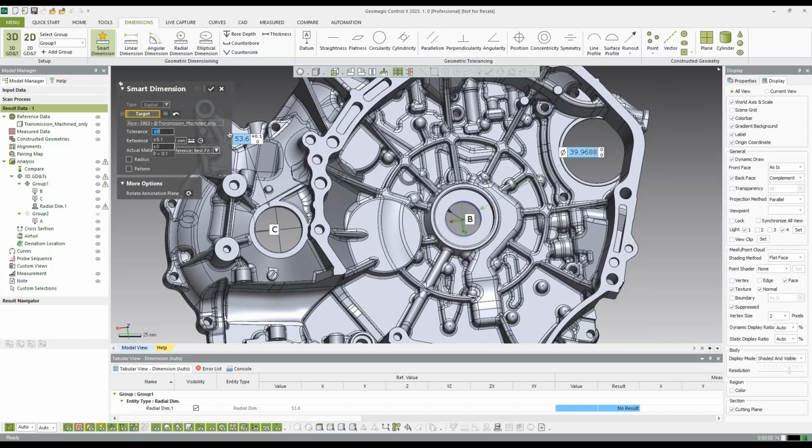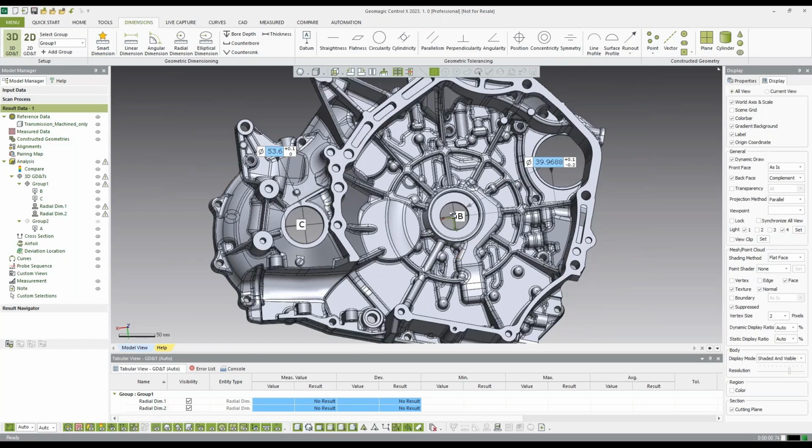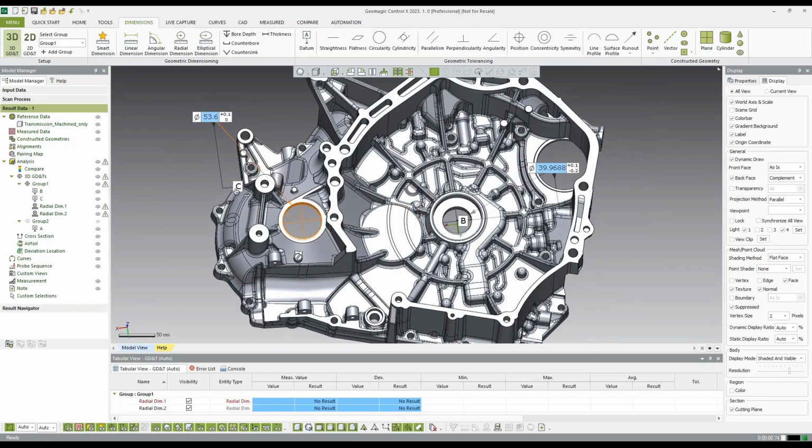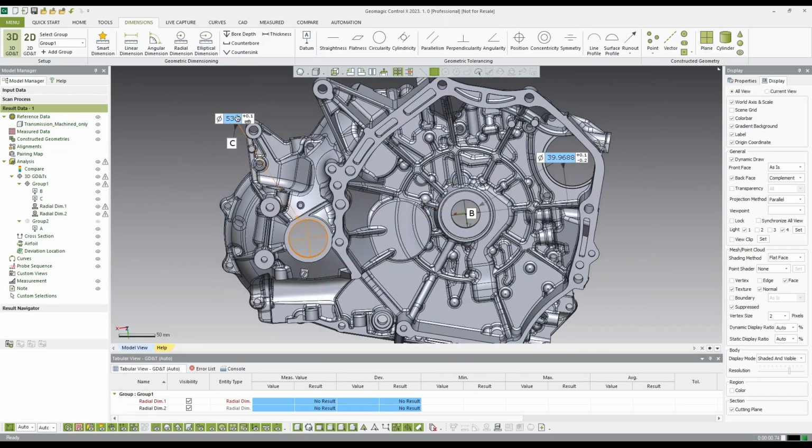And then you always have to put minus first. So remember, if I did minus 0.2, and then again using the tilde, 0.1, it stacks in really, really easy. And then you'll also notice as I add these dimensions and my tagging and everything else, since I picked my datums here, it's going to automatically attach that stuff.